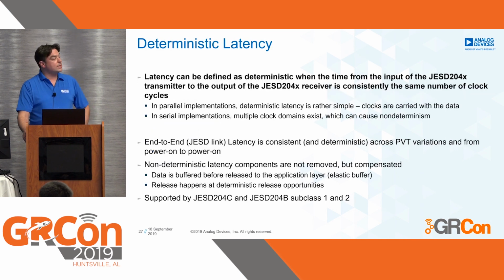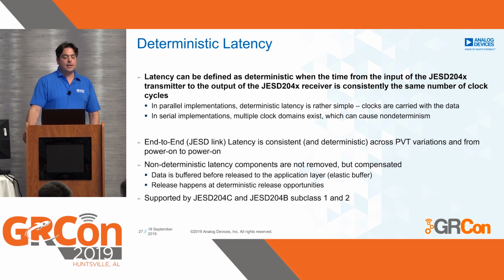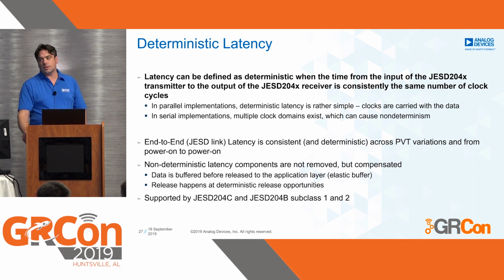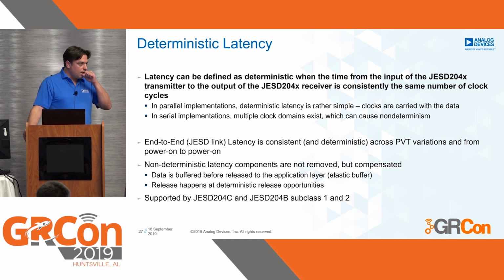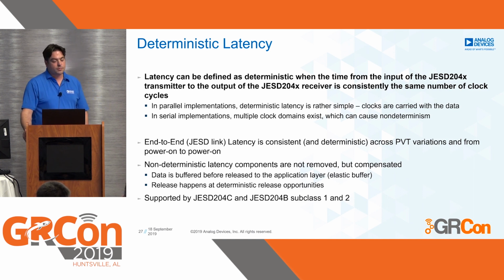So what is deterministic latency? Latency can be defined as deterministic when the time from the input of the JESD204 transmitter to the output of the receiver is consistently the same number of clock cycles. In parallel implementation, this is rather simple because the clocks are carried in parallel with the data. In serial implementation, this is a bit more difficult because there are multiple clock domains.